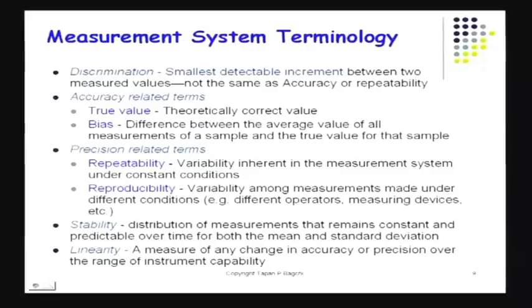in the measurement system. Then of course, we've got something called repeatability, and repeatability is actually the issue of using the same gauge and applying the same gauge again and again. This would be done by the same individual, the same operator, and basically what you'll end up doing is you'll apply the same gauge and you'll end up with different readings, and those readings would be caused by the gauge itself, and this is the issue of repeatability.